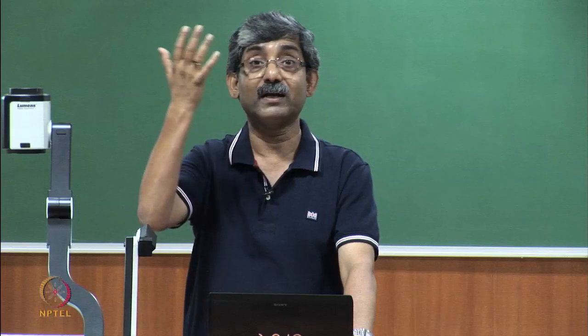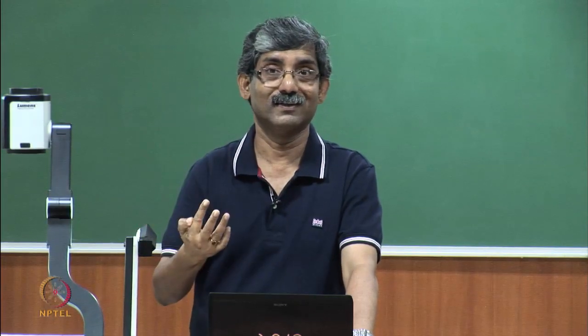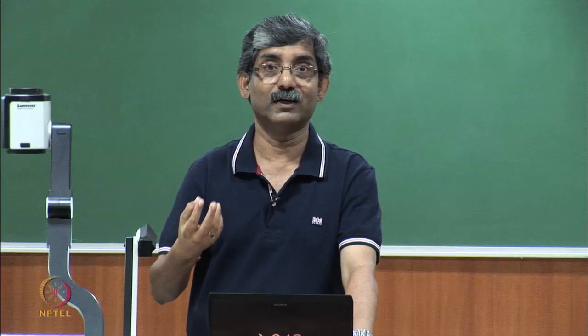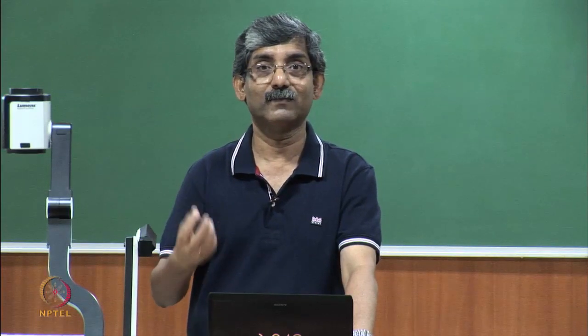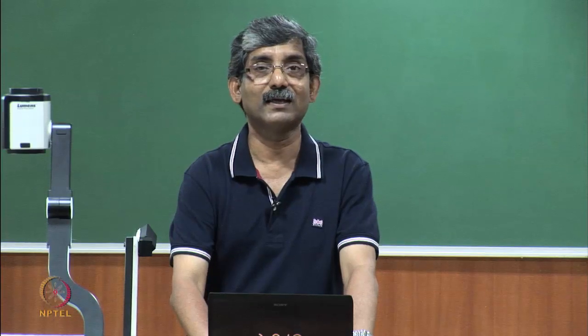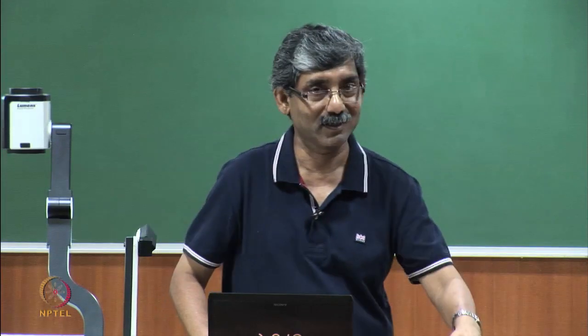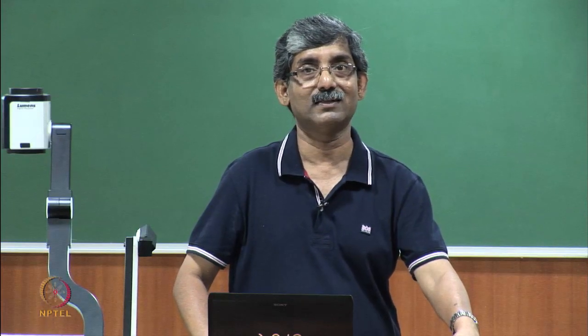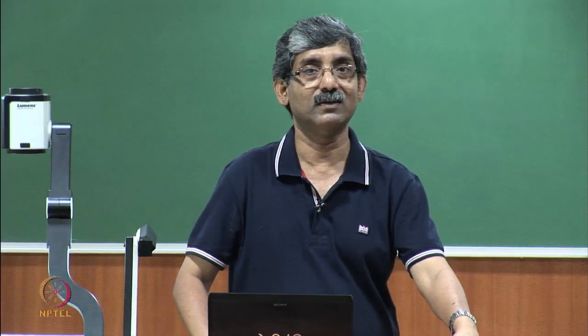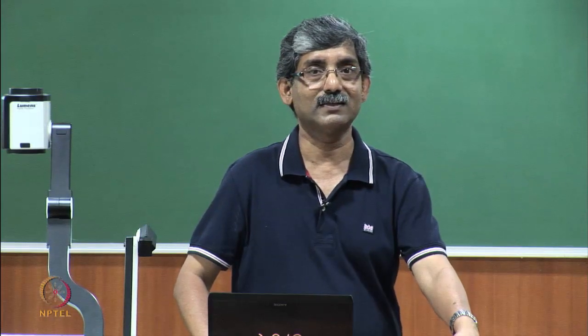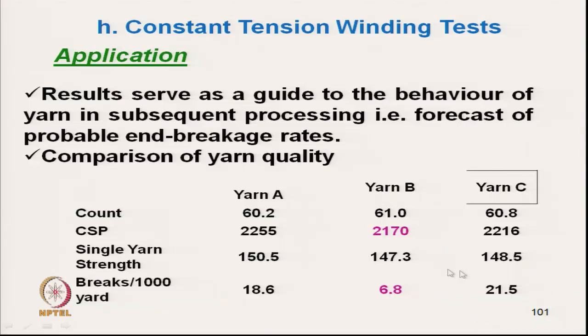Now, which yarn should I purchase? If someone tells me, I will definitely go for this yarn, it has a higher CSP, higher single yarn strength. If we ask which one is the stronger yarn, with higher CSP and higher single yarn strength, it is a good yarn, without testing the dynamic mode. Now, once we test the yarn in dynamic mode, then our decision will be entirely different.